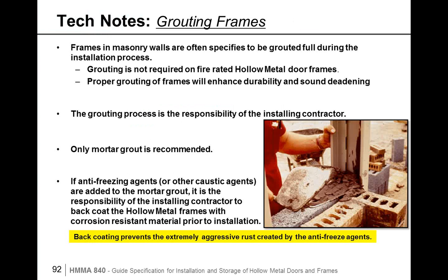In these technical tips, there's one dealing with grouting of frames. Grouting is part of the installation of masonry frames. It is not a required part of installation, and not a required part of fire coating and labeling, but specifications do require it, and contractors will do the grouting of the frame as the wall is being built up.